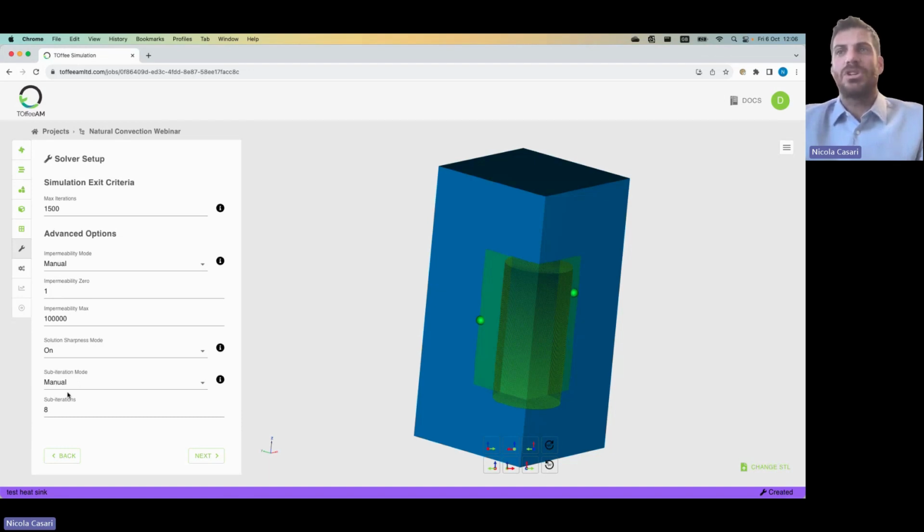Typically for only pressure losses, or for incompressible problems, just leaving it at one is enough. A better convergence is required if we switch to this kind of problems in which the variables are tightly coupled.